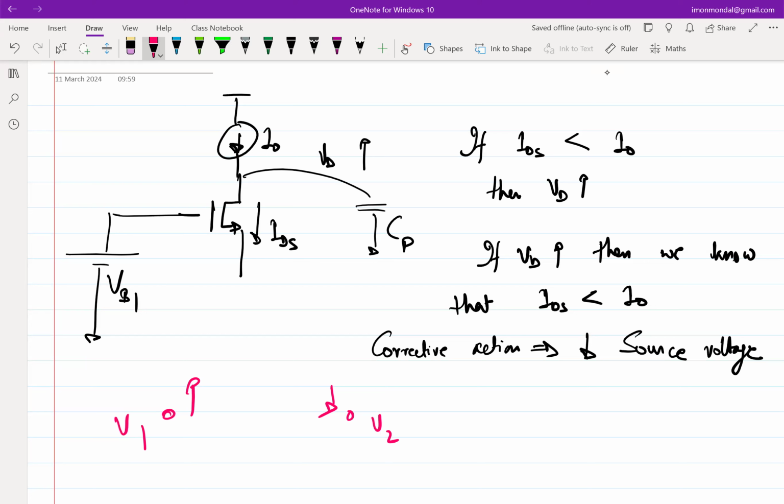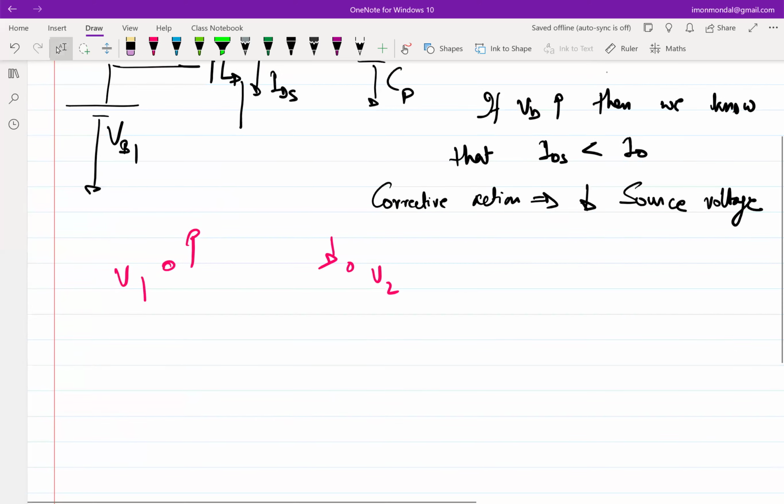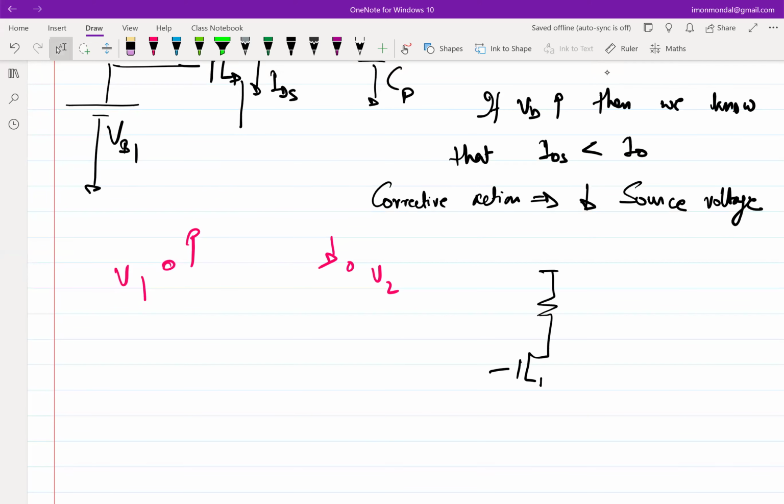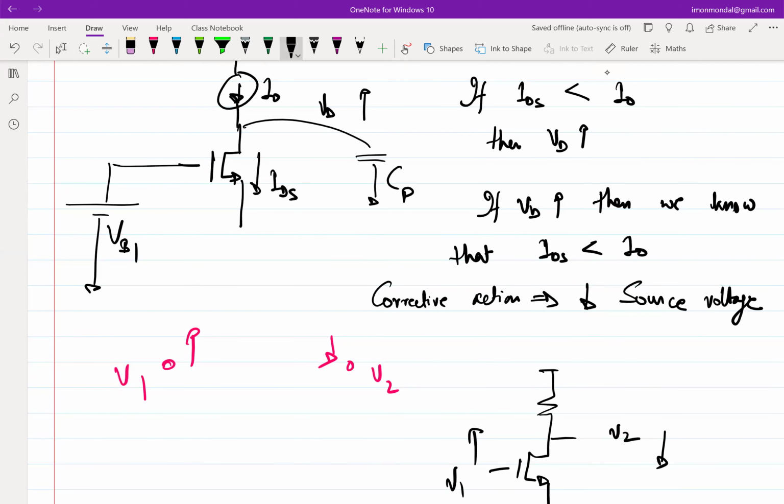Yeah, right. So it's like a common source amplifier does that. Our simple common source amplifier does that. If one terminal increases, the other decreases. Let's say this is V1, this is V2. If this increases, this decreases. Seen this? Okay. So all we have to do is maybe apply a common source amplifier type of topology between VD and VS. Correct? What is the requirement again? If this guy increases, I have to decrease this, and it has to be done automatically, obviously, right?